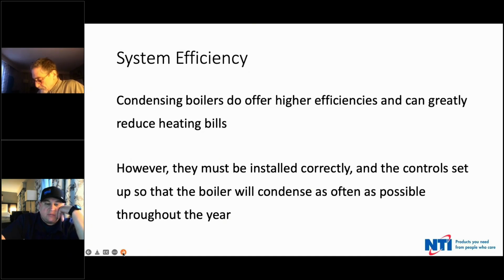Because if you run a system like a heat pump, they constantly run. Heat pumps constantly run. You don't want them to shut down because if they shut down, you start to work that compressor up. So, these are things that, like you said before, every time the boiler goes on, it starts the igniter, it opens the gas valve, it starts the fan, it's working all the components.